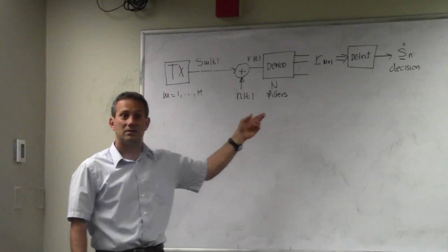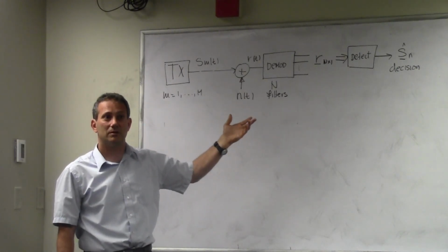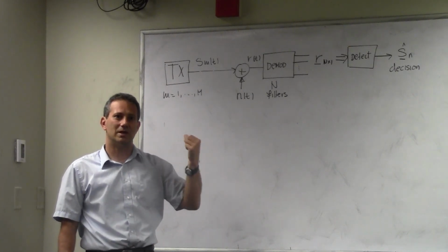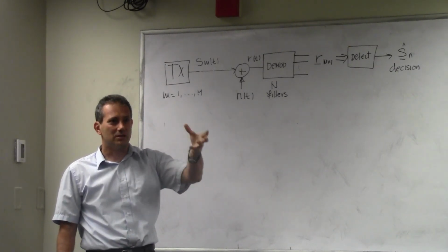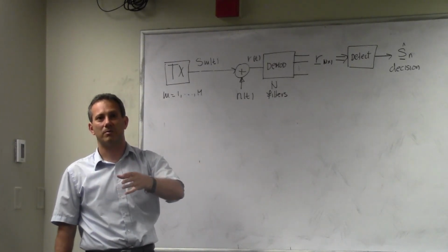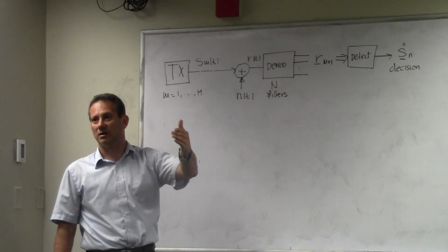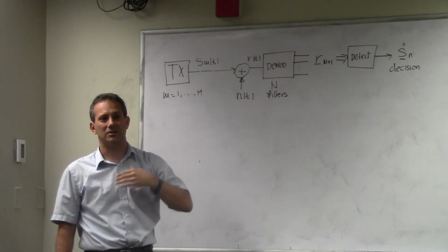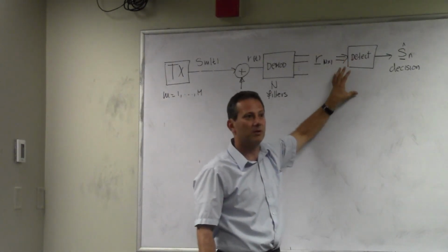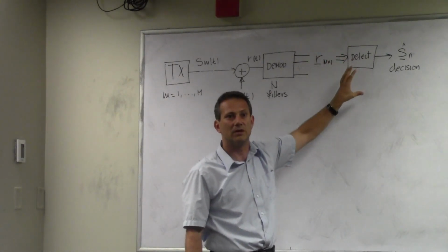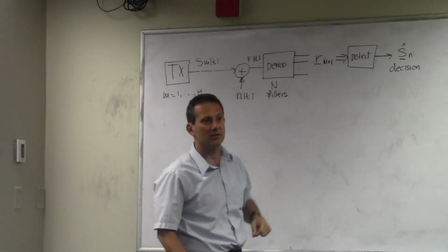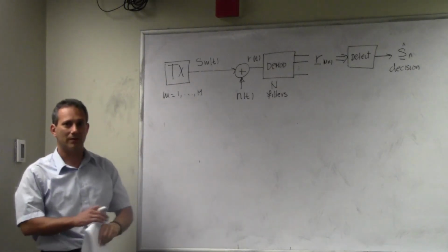And guess what? These signal-to-noise ratios that I'm talking about here are the same ones I talk about in PCS and other classes when I say the receiver comes with a signal-to-noise ratio required for its proper operation that goes into receiver sensitivity calculations. This is where we take a macroscopic look and say, okay, for this to work properly, with the given modulation, coding and all that, I need to provide 12 dB here or 35 dB or whatever is the ratio that I need to provide.